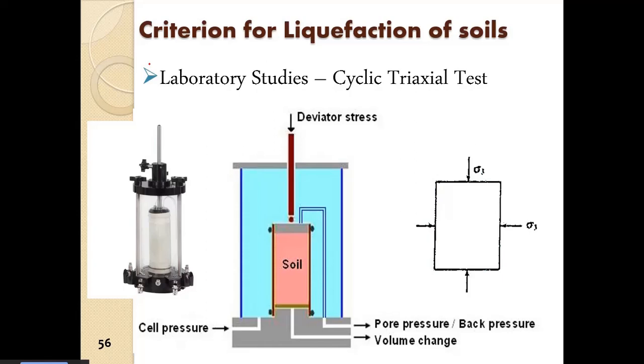In the undrained case, positive pore pressure will develop, leading to reduction in the effective stresses, and ultimately the soil will liquefy. And then we saw that that criterion alone cannot explain the various factors which govern the way soil behaves